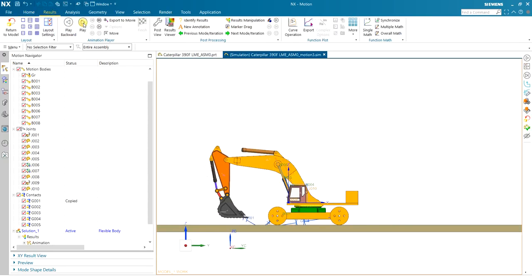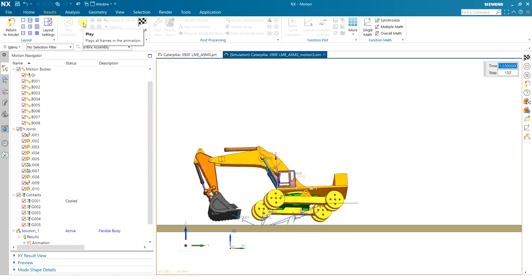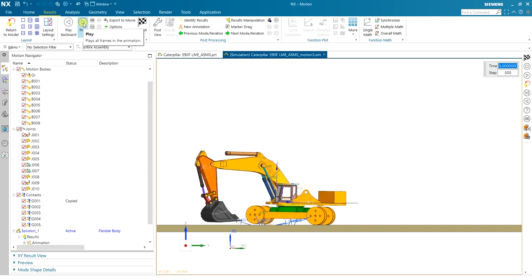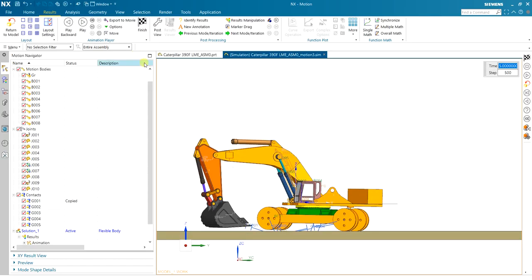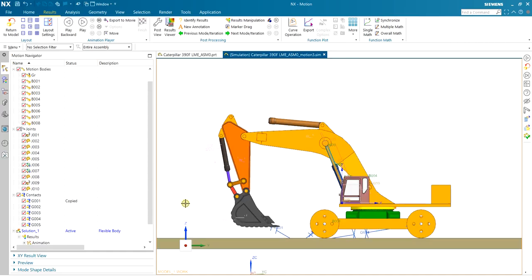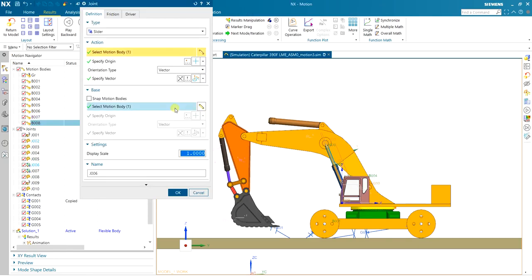And let's see the results. As you can see, the contact is really stiff, it's bouncing up and down. So I'm going to relax the contact a little bit. Also that 100 millimeters wasn't enough, was too fast, so it's not a good idea to move by initial displacement.